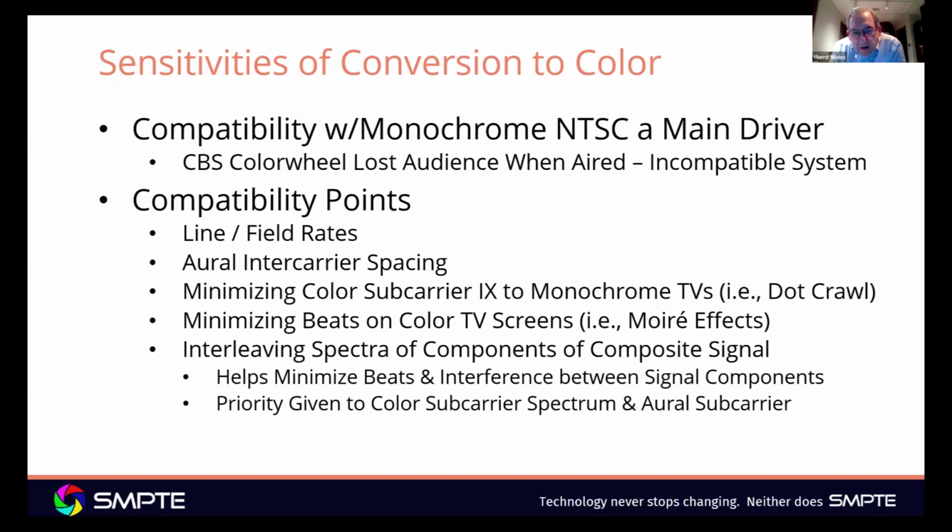And then the color subcarrier spectrum and the aural subcarrier were given priority when it came to interleaving because they were closer to one another in the overall baseband spectrum than was the aural to the visual carrier.